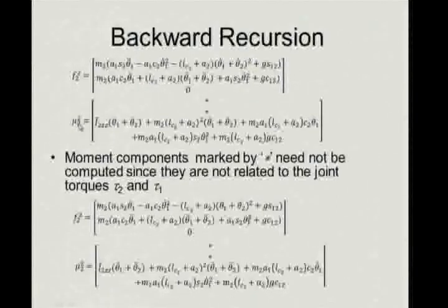Okay. Now, get smart. You realize that you want to find components which are eventually along the joint axis. Now, all the joint axes are about the z direction. So, it is unwise to try and compute these two terms. So, you just do not compute the moment about these two terms, just compute the z term, it is here. I am not computing the rest because it is not needed.